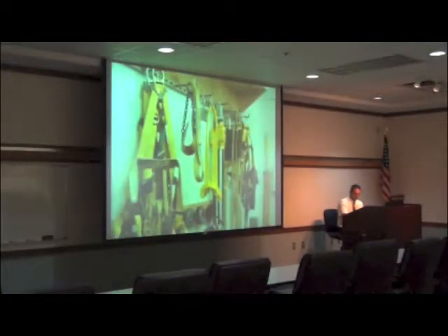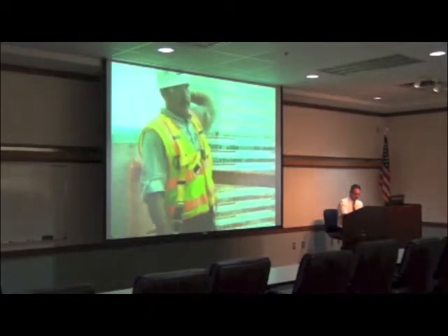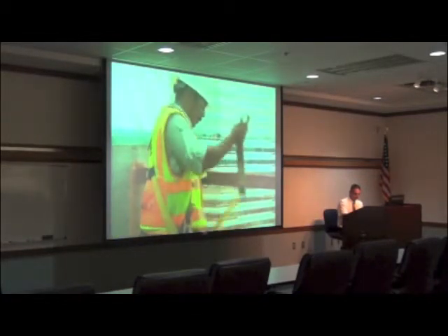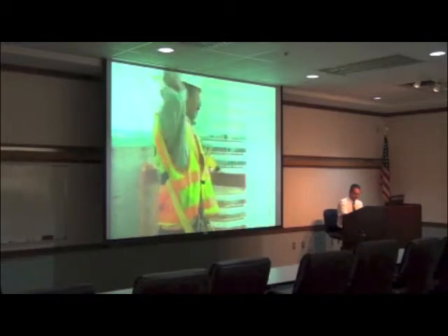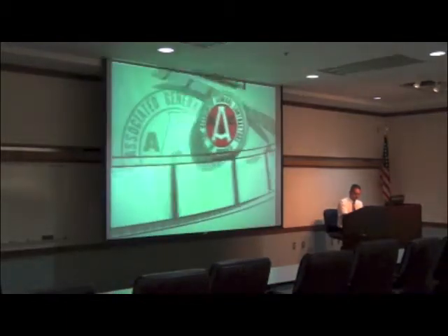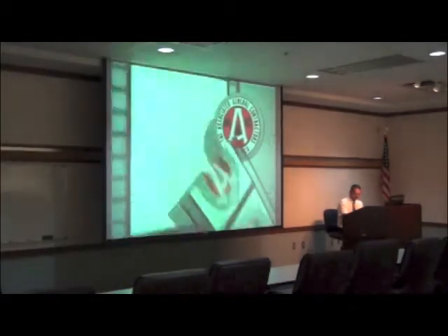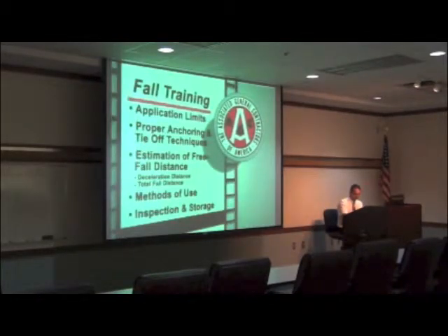Before using a personal fall arrest system, make sure you have been trained in the safe use of the system. This training should include application limits, proper anchoring and tie-off techniques, estimation of free fall distance, including determination of deceleration distance, and total fall distance to prevent striking a lower level, methods of use, and inspection and storage of the system.